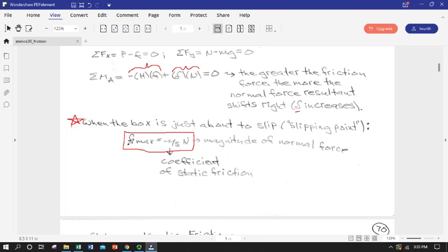So this is basically our additional relationship that friction relations give us that we're going to add to our conditions of equilibrium and help us solve problems where friction is involved. We will pull this out if and only if we know the system is at imminent slip. So look for words in problem descriptions or out in the field in some kind of write-up that indicate maximum criteria for no slip.